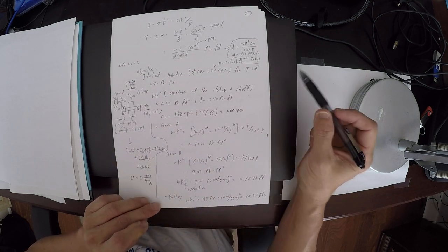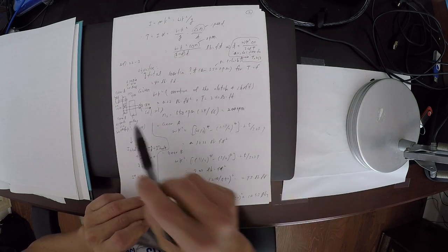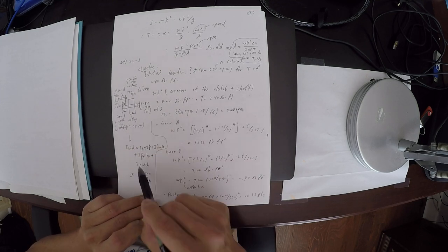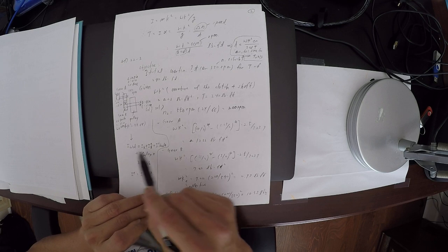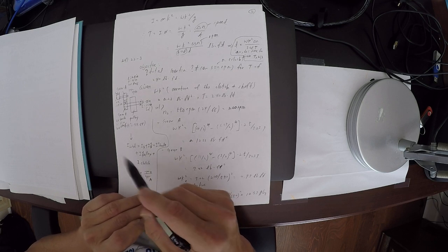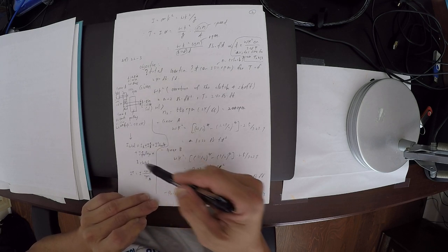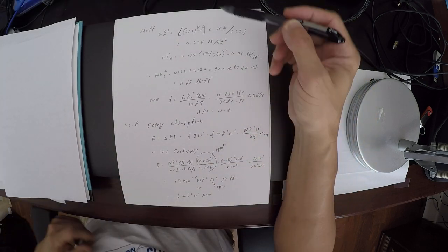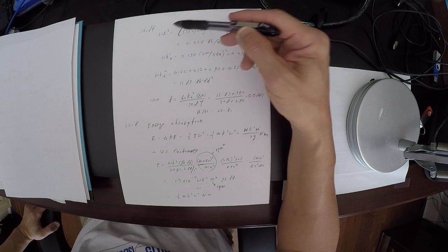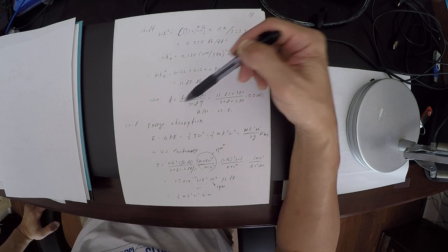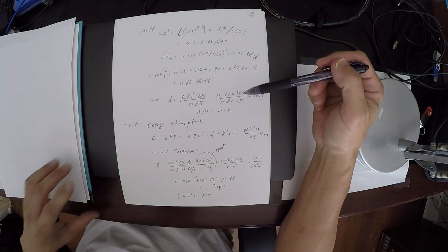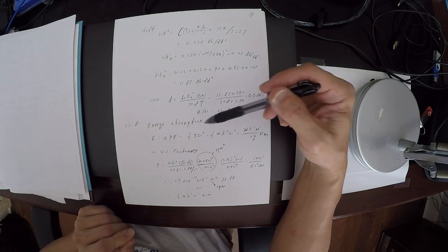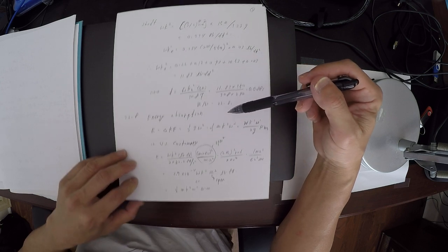This is G unit system where you have multiple gears, and so we actually tried to evaluate all the inertia with the given gear ratio, and then we calculated the inertia term, WK square, and then found out the time, T. So what we will continue on today is to discuss a little bit about the energy absorption.